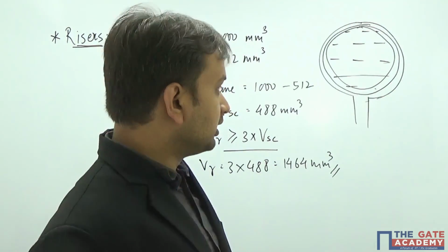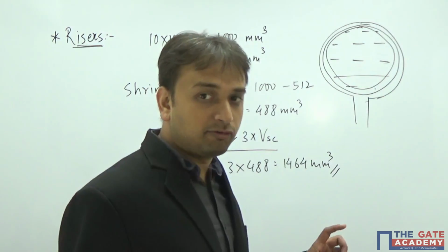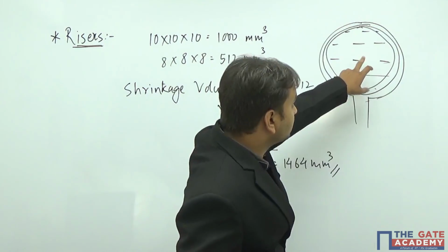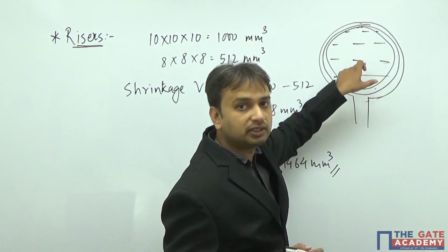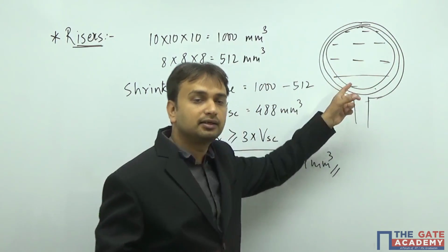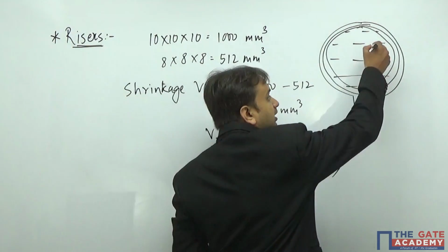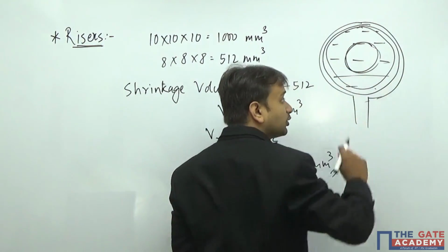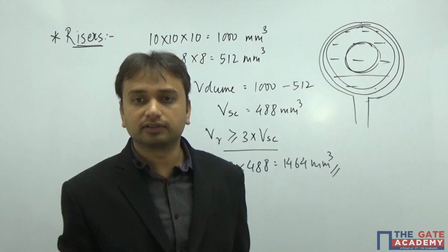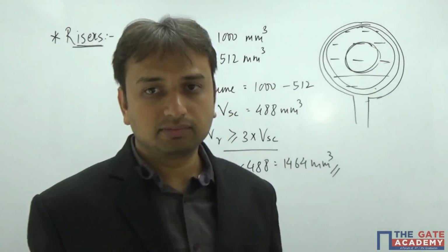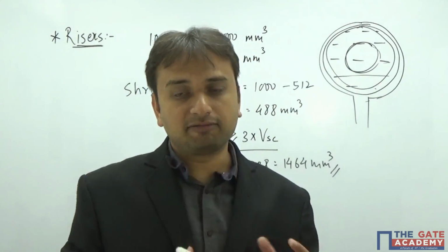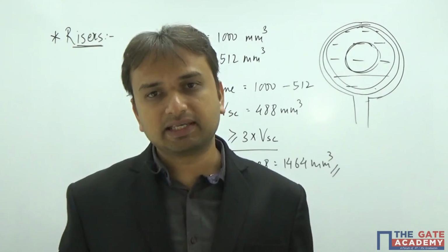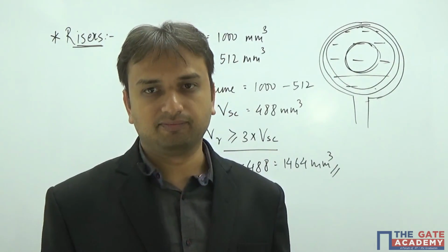Very good. So this spherical riser, although if you talk about the molten metal at the core of the riser, this is going to stay in molten state. This particular part is going to stay in molten state for a very, very long time, because of course these spheres have minimum surface area, and that's why the heat transaction is the least, right?